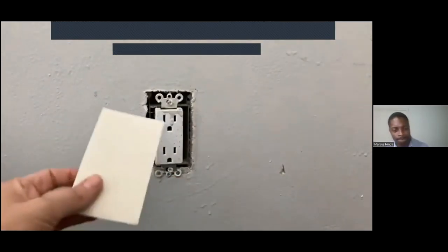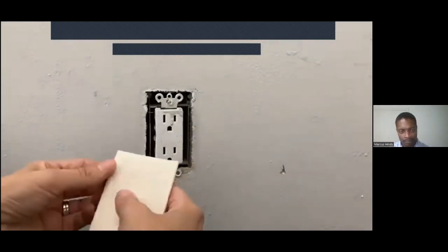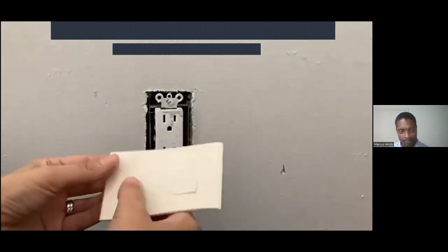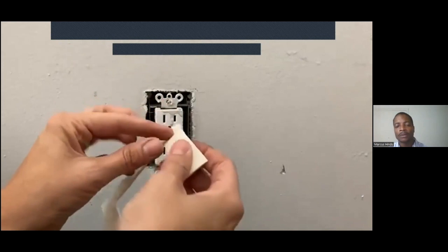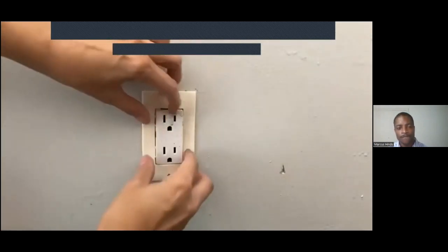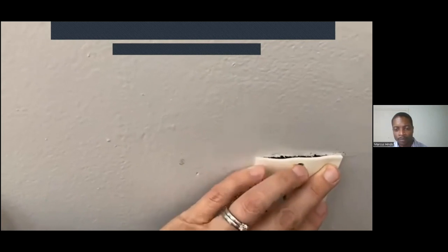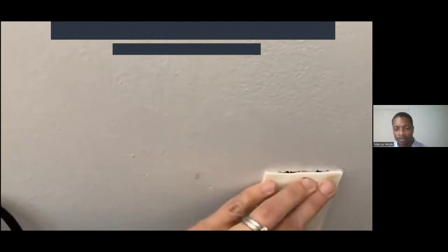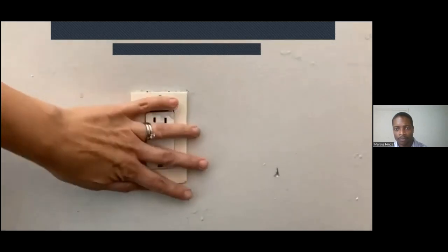Then I take my foam pad and tear along the perforation that I want, and pop out the holes for the 2 screws. And I place it over top. And it's not bad. There's a bit of a gap there. So I probably will caulk this one, because even when that presses against, there's still going to be an air gap. So at that point, I'm going to put the plate back on.